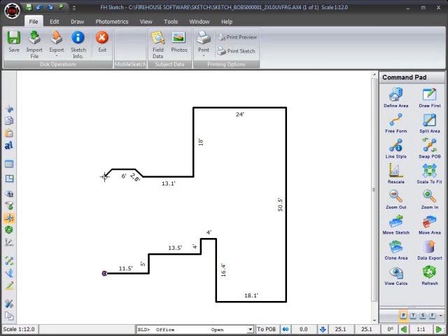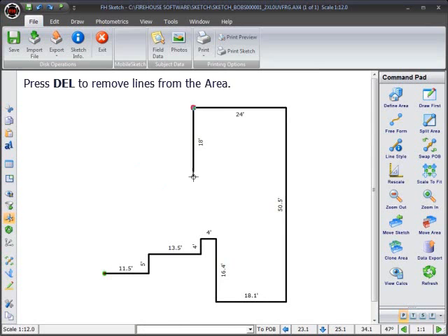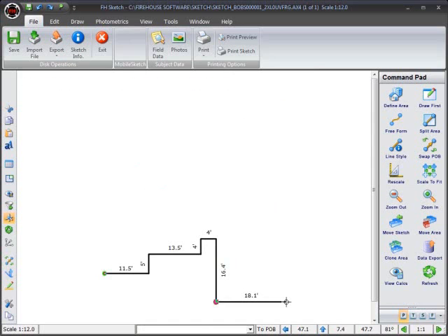Let's say that your notes show a measurement of 28.1 feet for this particular wall. Assuming your measurements in your notes are accurate, you'll need to check for errors in your drawing to ensure they were input correctly. After looking, let's say you find that the 50.5 foot line drawn here was actually supposed to be 53.5 feet long. To correct this, repeatedly press delete until the 50.5 foot line is removed. Now enter in the correction of 53.5 feet up.